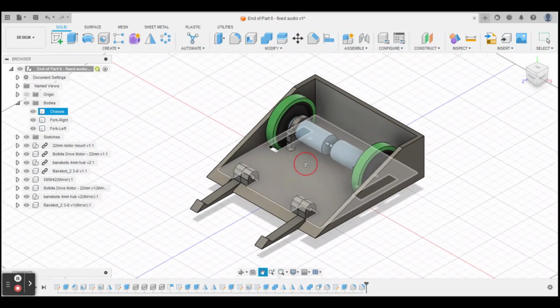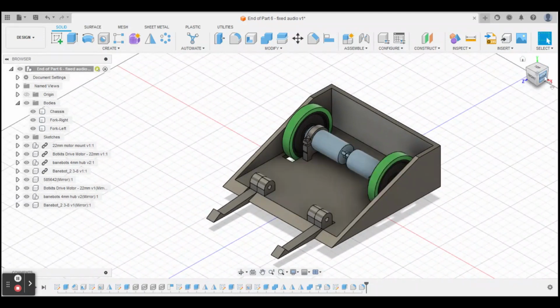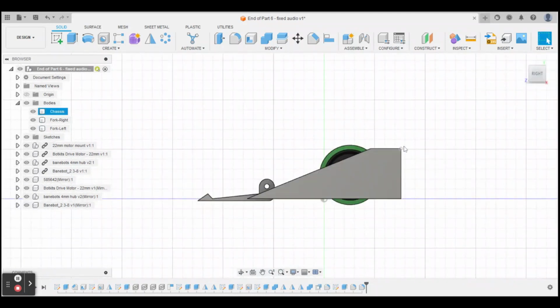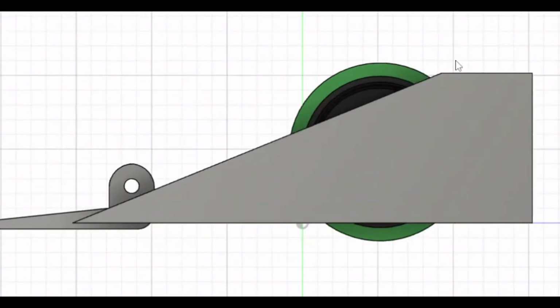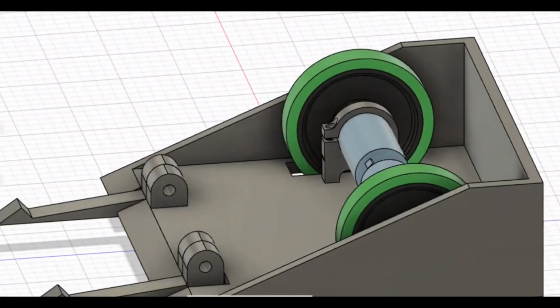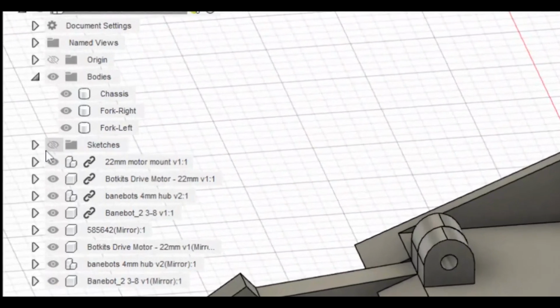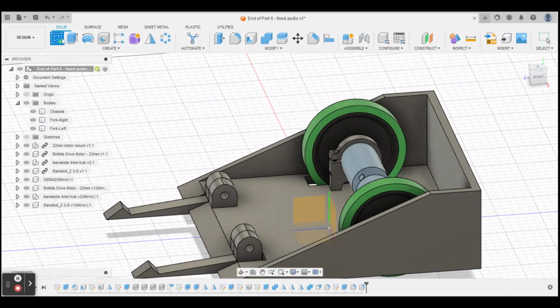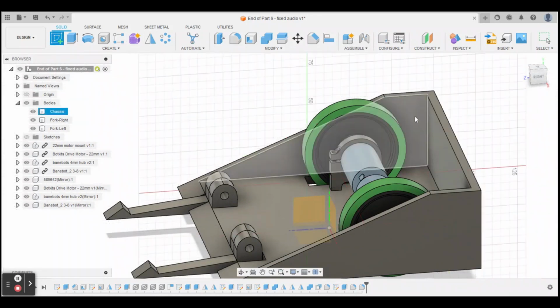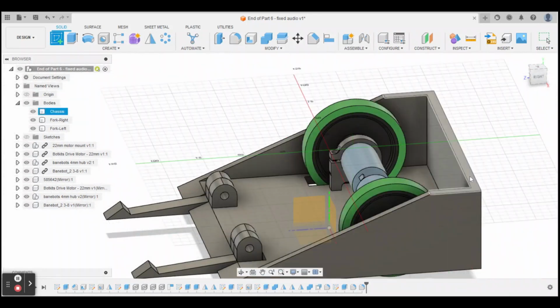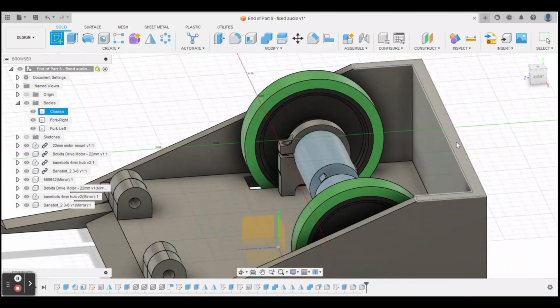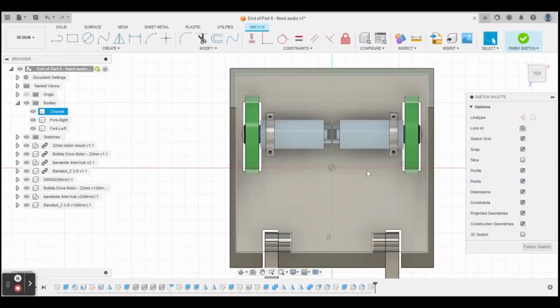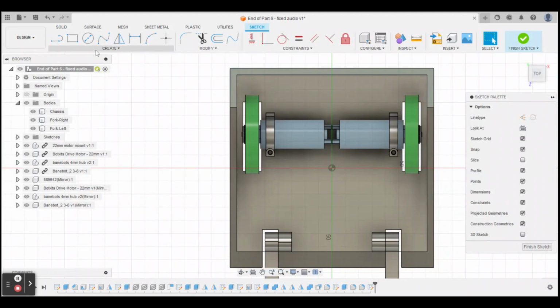So now let's make a top to the bot. Actually, 2 tops. I'm gonna make a top for this section here. And we're gonna make a top for this section here, okay? So before I create a sketch, I'm always gonna unclick the eyeball so I'm not drawing on a sketch instead of the body. I'm gonna click create a sketch. Now what face do I wanna draw on? I wanna draw on this top face here. So I'm gonna click on this face.